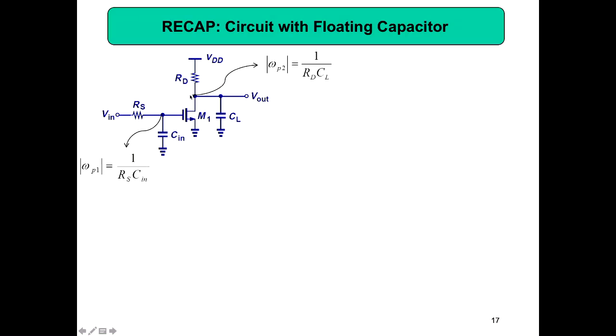Why do you need to find the pole? Because when you have a pole in the circuit, or when you see a pole in the frequency response, or in the Bode plots, all are the same. Then your gain is decreased by minus 20 dB per decade. So that is not good for your amplifier. So we need to find the pole.